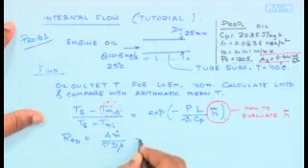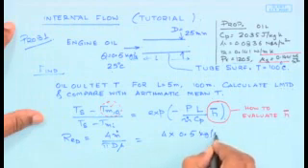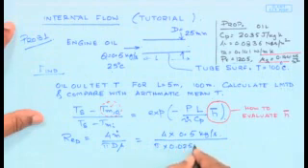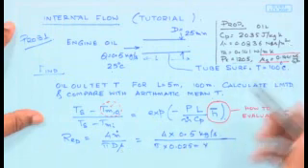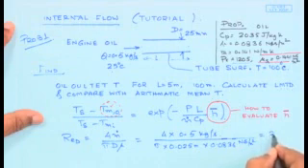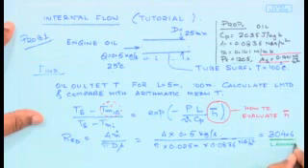It's a very straightforward calculation. So, 4 into 0.5 kg per second, which is your mass flow rate, pi times 0.025 meter being the diameter, and the viscosity, and this viscosity is going to be the bulk viscosity. So, therefore, it is going to be 0.0836 Newton second per meter square, which would give you a Reynolds number of 304.6. And now, if you look at this value, this definitely tells you that it is going to be a laminar flow, since the value of Reynolds number is only about 300.